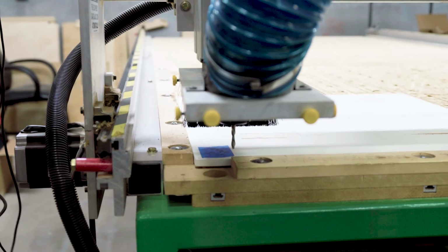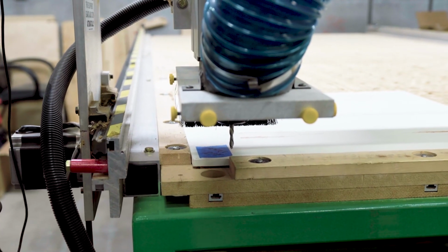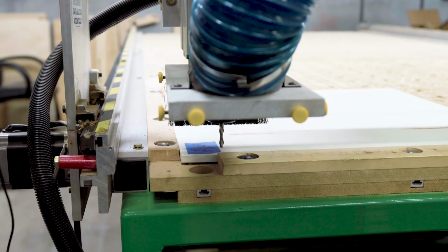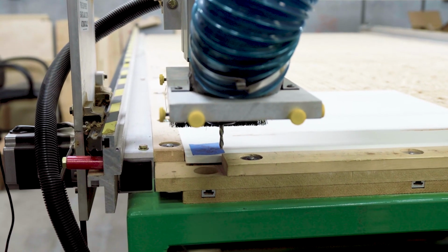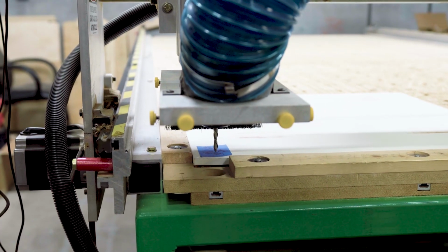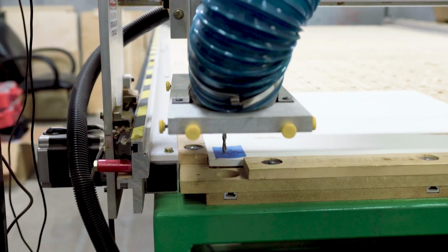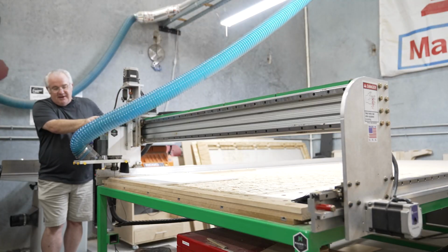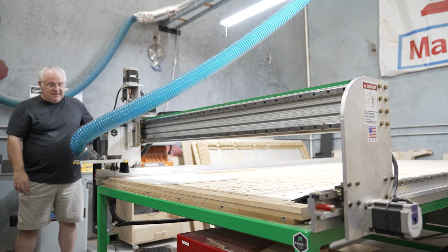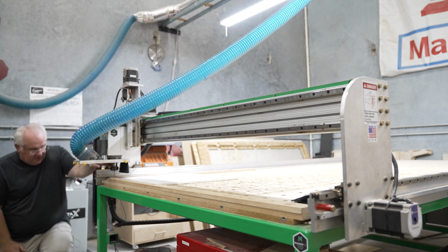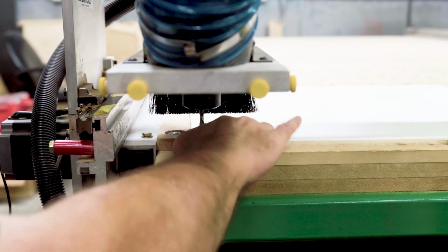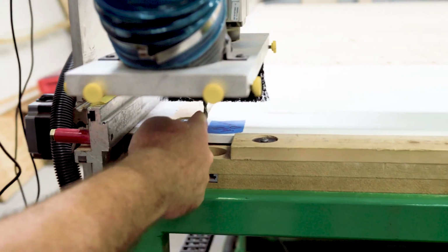I'm going to put it in slow mode now so I won't make such large movements. And I'm going to move over to this corner. Now, this is again a question of how precise do you have to be. If I'm cutting something out, I don't have to be that precise. I can get it just pretty close. And what you'll want to do is visually, in setting the X, look from this direction and make sure the center of the bit is